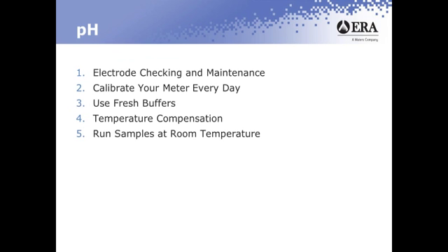However, pH has very tight limits in the DMR QA study. The limits are plus or minus 0.2 standard units, or SU. Due to these tight limits, pH traditionally has the highest failure rate in the DMR QA study. So our points of topic are going to be designed to help us perfect our testing by maybe 0.02 to 0.03 SU for each of the topics. And if we look at the limits that we have, that's about plus or minus 10% of our range.